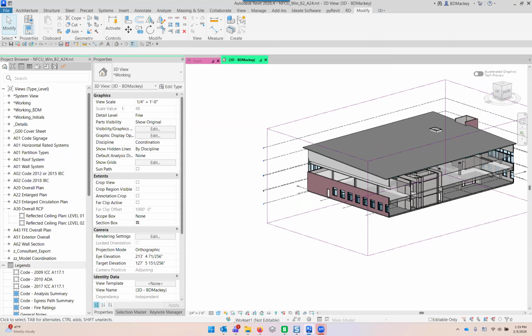First off, one thing that scared me is text on sheets. I think that's a huge no-no in my personal opinion. I never, ever, ever do anything on a sheet. In my mind, a sheet is merely a placeholder for a view. So I would never put text on a sheet. People say, what if it's just a one-off sheet note? Inevitably, somebody's like, oh, can we add that to this sheet? Can we add it to this sheet? And then it's not going to be linked. So even if it's just general notes for a sheet, I would never put those in there.